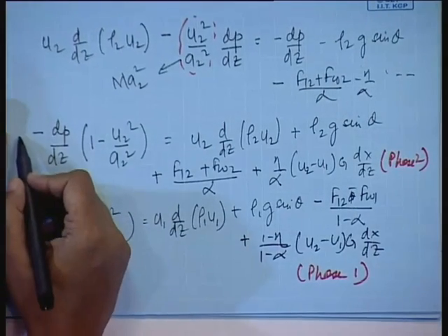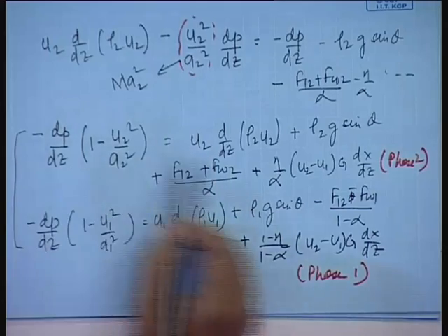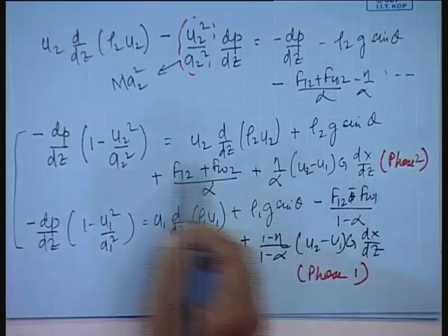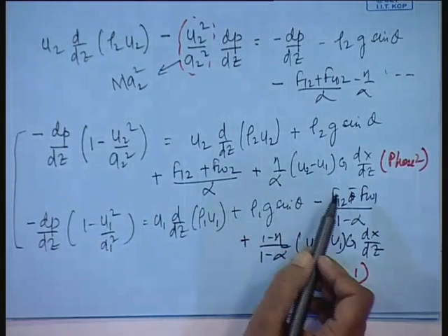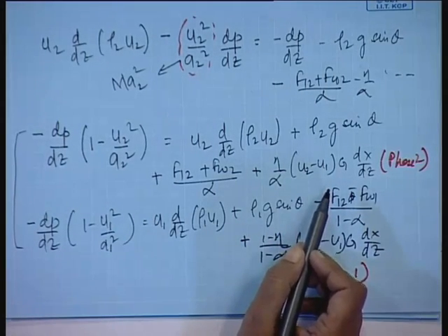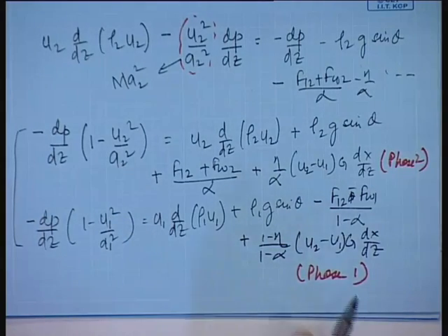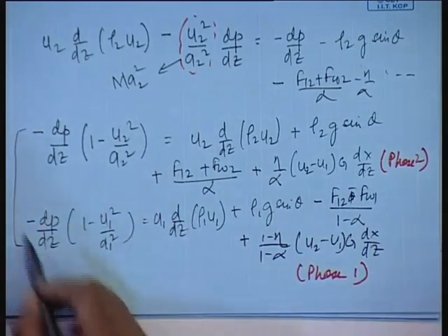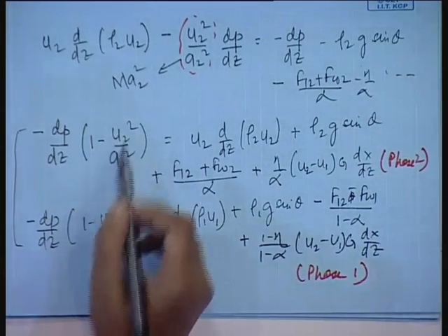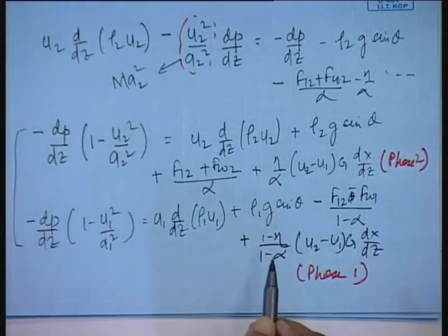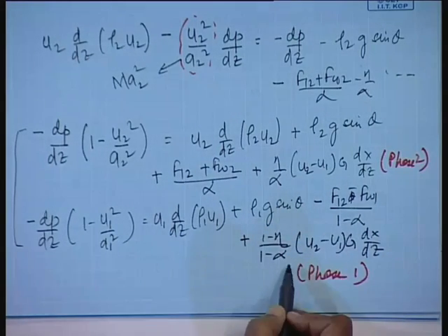So, from these two equations what do I get? Phase 2 is choked when u2 square equals a2 square, all of us know it, and we have derived it from this particular equation. Agreed? Phase 1 is choked when u1 square equals a1 square, this also all of us know. When is this two phase system getting choked? We cannot say u1 equals a1 and u2 equals a2 will guarantee the condition of compound choking, because there is a good amount of alpha part also here.